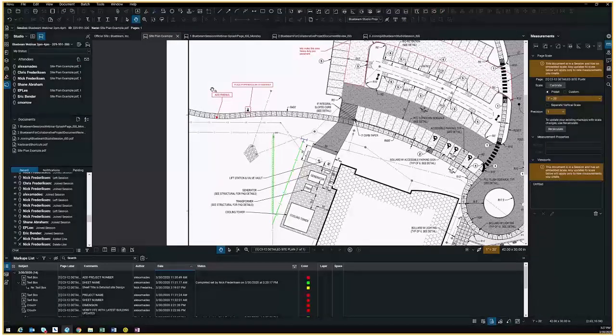They don't have to have a paid version of Bluebeam. They can download the free Bluebeam view and do all of their work on commenting within that session. That, in turn, everybody can see at the same time. Everybody can start updating at the same time, all the way through the process. When the process is done, you can export the drawings out to keep the markup list, and you can also export out a summary of all of the work that was done on there.